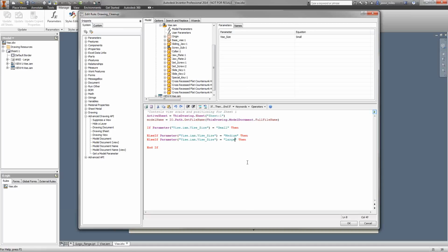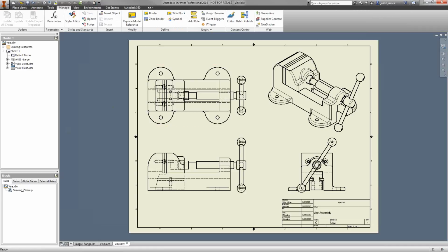And then just remember, case sensitivity. We've got to pay attention to that while we're referencing these parameters and features or parts. So just remember that when you're actually typing these in, if you're not selecting them from up here at the top, whether in your parameters area or your names window. Okay, so once I have that, I'm going to go ahead and say OK, just to verify that I'm not getting any errors so far. Okay, so far so good.